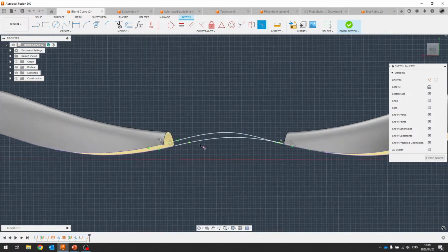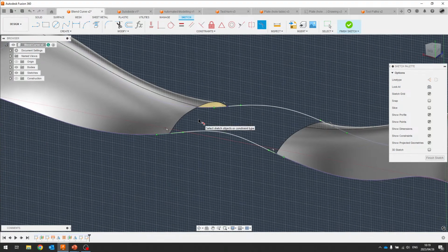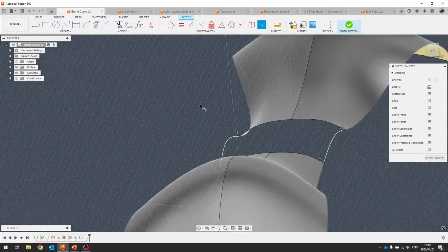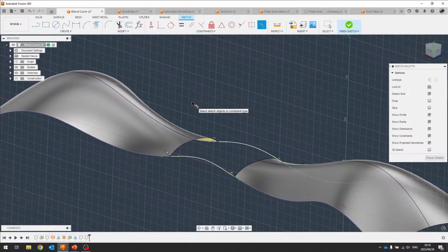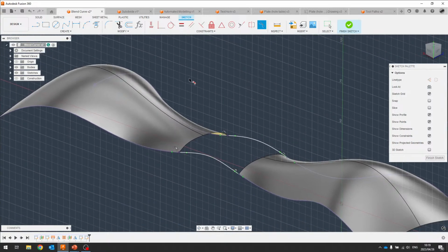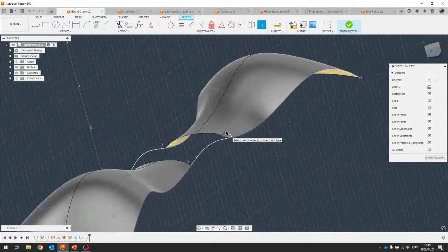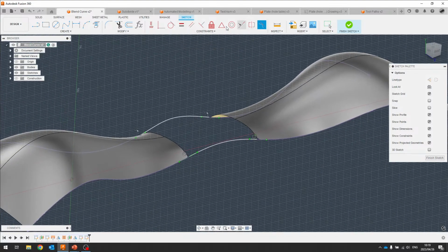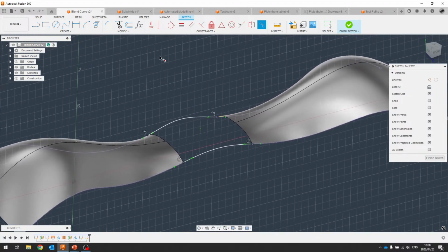So that just helped change it from tangent to curvature, seeing that the curvature option didn't give us a good result on that component. So just a little bit of a thing that I noticed there, specifically with this example and that blend curve, but we have that ability to modify it and change it after the fact if we need to, because it's using those standard constraints from your constraints panel. So it's a nice quick one there for blend curve.